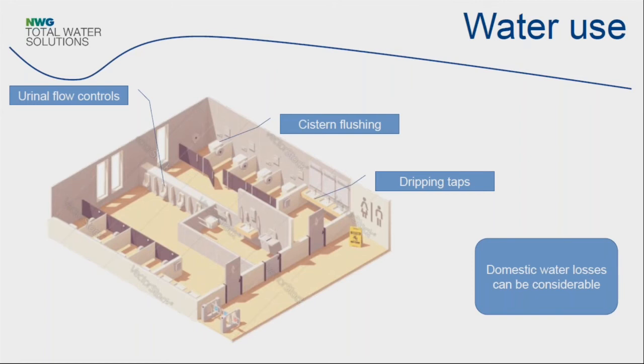If you look at cistern flushing, I did an audit in a very large office a couple of years ago where they had very new, very modern cisterns which only offered about 4 litres per flush, which isn't a great deal. A standard cistern might offer 6 litres, the older ones maybe 9 or even more. The maintenance manager told me they had a rolling programme of taking out these low flush cisterns and putting in 6 litre cisterns. The reason was, without putting too fine a point on it, the 4 litre flush just wasn't enough. So people were flushing the toilets twice or 3 times sometimes.